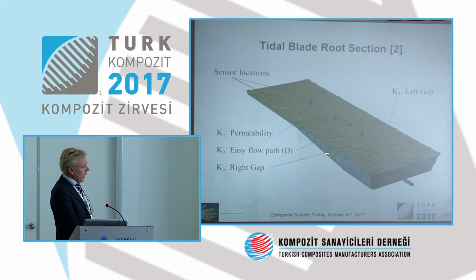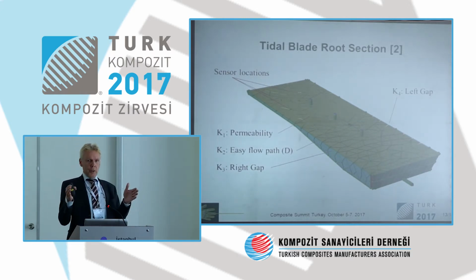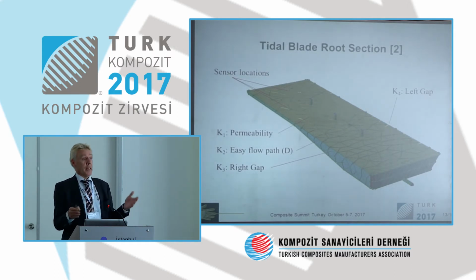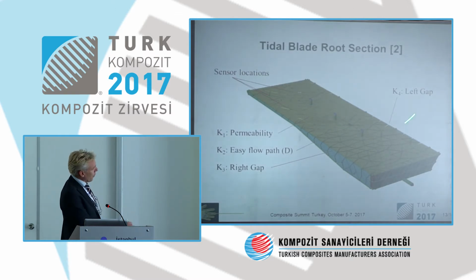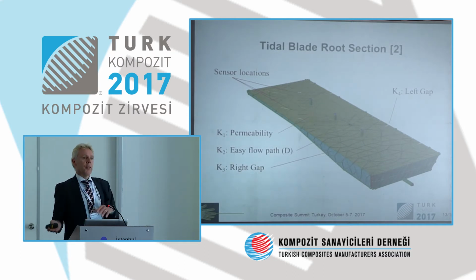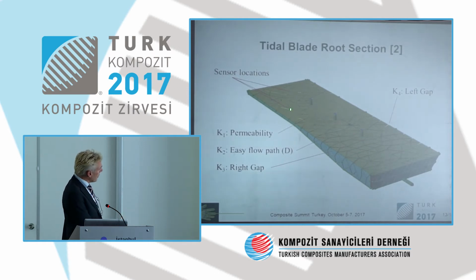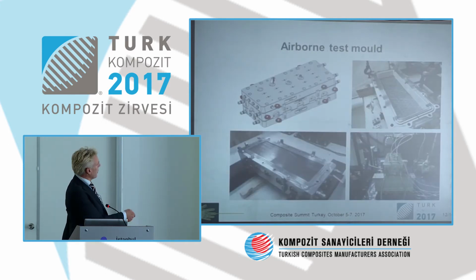And then we have the left gap and the right gap, because it's possible that the preform is not symmetrically exactly in the middle of the mold. Maybe the gap on one side is 0.1 millimeters, on the other side 0.5. So with those 4 parameters, we can try to match the flow, the model, to the feedback from the sensors. And the sensor locations, and that's very hard to see in this slide, unfortunately, we have several points on top which corresponds to the locations you see here. And we can use those to check, to monitor the flow front.